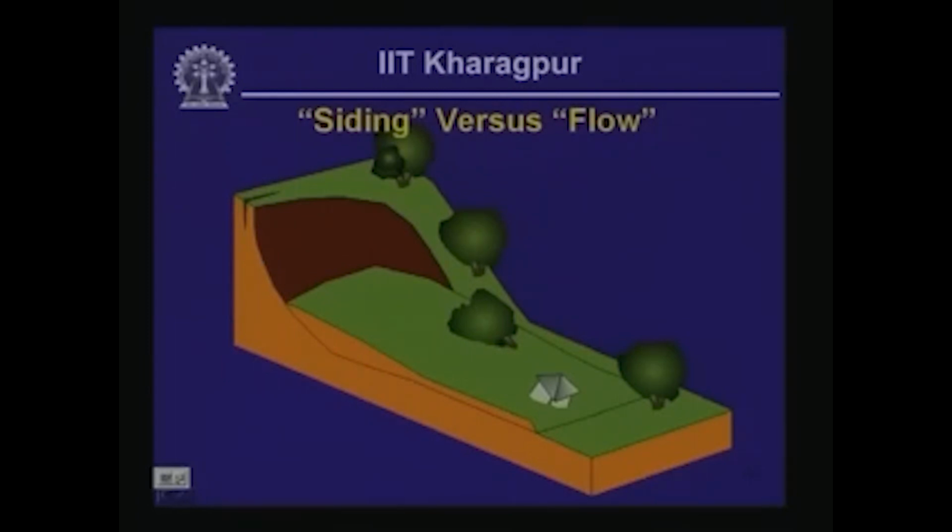You should also look at the damage this type of slide could cause, which is illustrated by the tree that has tumbled downslope, and the building which was constructed a little bit downslope. So this illustrates what could happen, and you can see from this schematic sketch that, because the unstable mass actually behaves like a liquid, the objects could float on top of this destabilized mass.